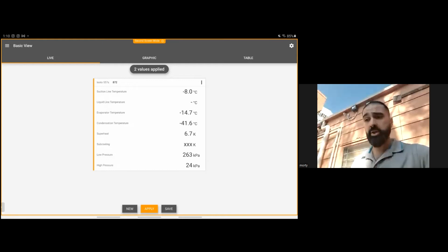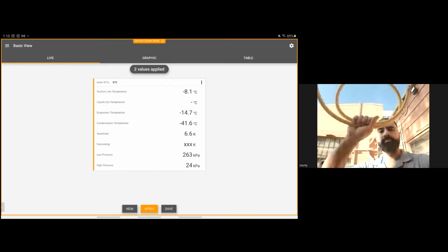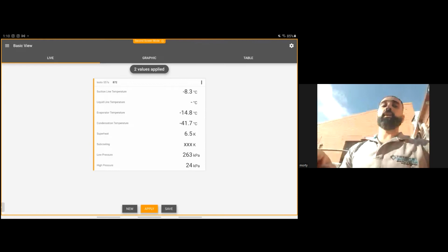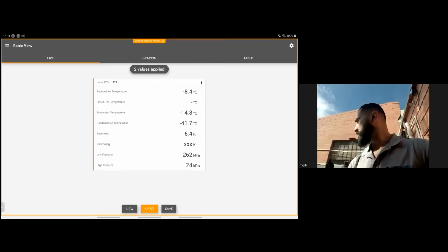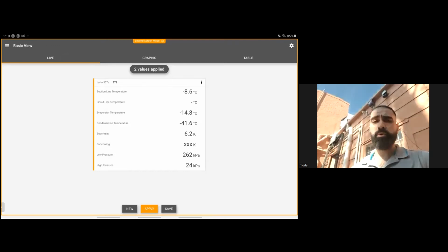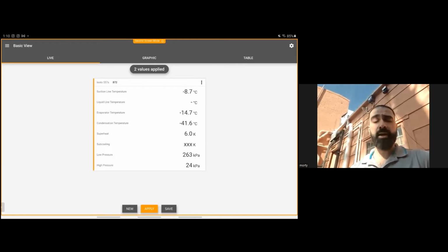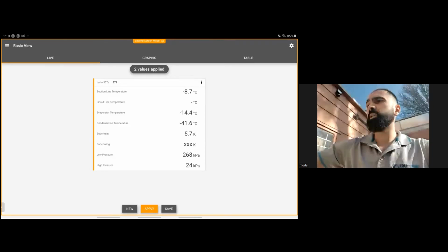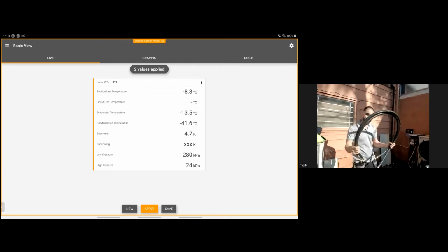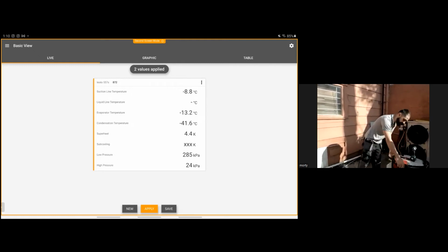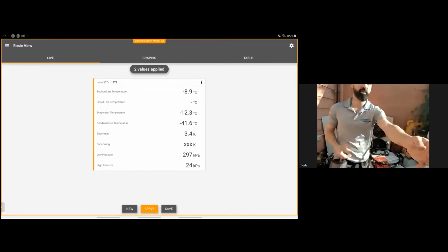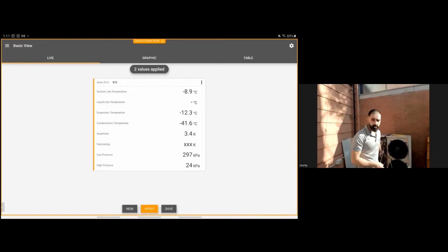Now, a lot of guys will use a standard hose, which you get with your gauges, like these. This is a 3/8, and you've got a 1/4-inch gauge as well. These can actually do the vacuum. I'm going to switch this off. They will do the job, but they are not true vac hoses. A true vac hose looks like that. These are vacuum hoses, and these are 3/8. Try to connect them directly into your system.